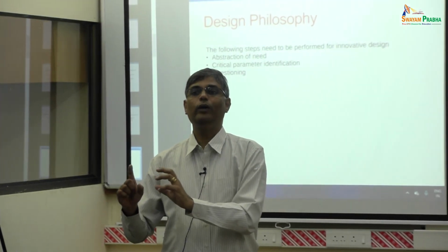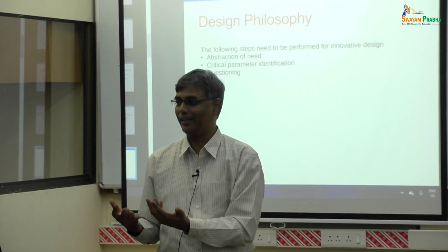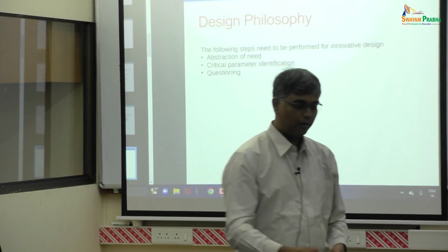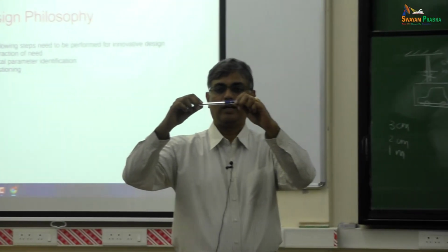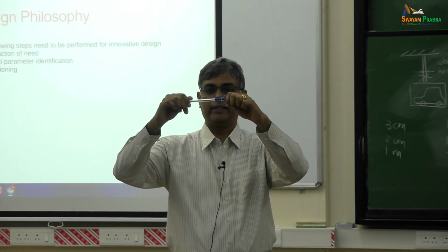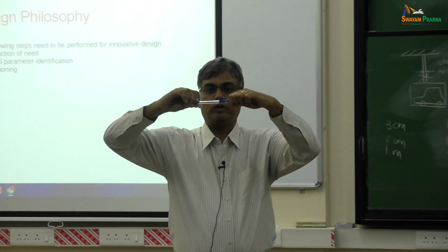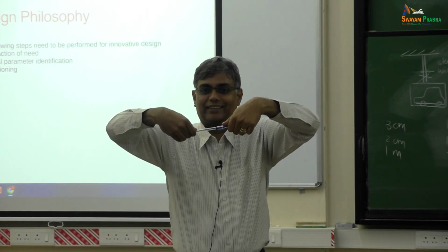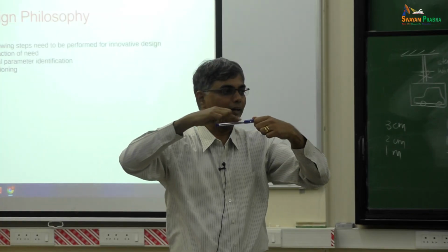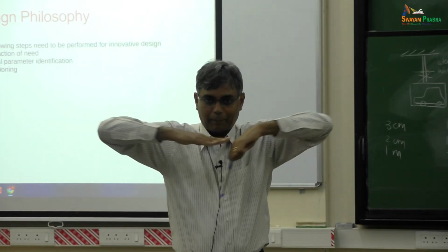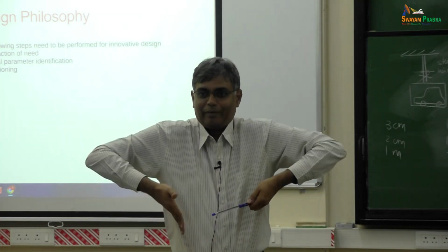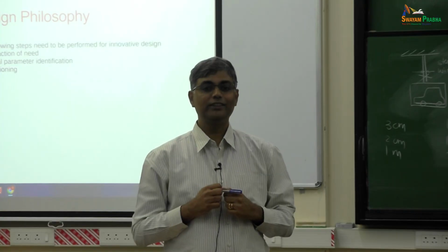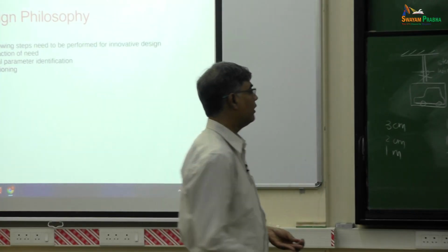So they just did a small static loading calculation, but what happens is, when you have a shaft of a car or a rail, it keeps rotating, and if you have a load, it's bending like this, but when it rotates, now it's bending the other direction. So the same fiber, if you look at the top layer, when it's like this, it will be compressed, and when it goes there, it will become extended. So compression, extension happens, and that causes failure. That is called fatigue.